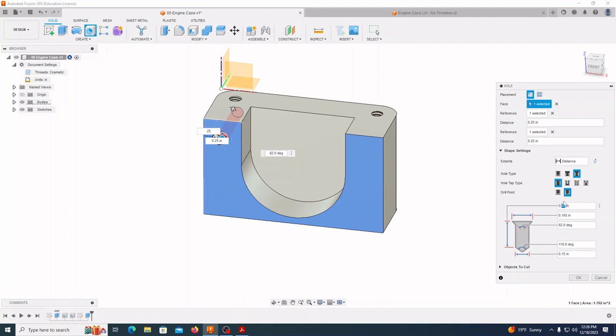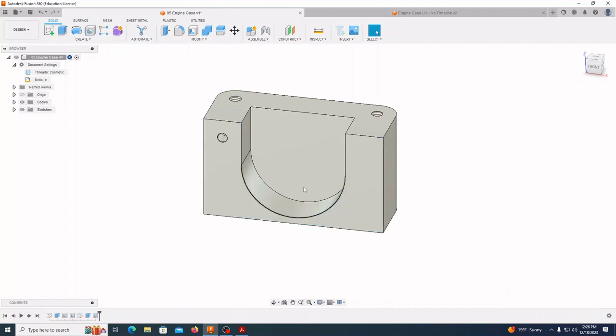The depth per our prints is 0.1875. The width of that is going to be 0.125. And on our countersink, what we're going to do is we're just going to break those edges 10th out. So we're going to take that 0.125 plus 10th out, which is 0.135. And then we press OK. And we have your first hole right there with the edges already broken.